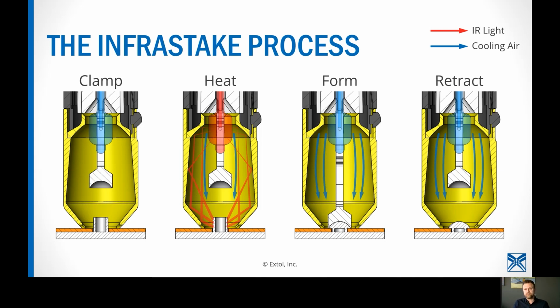Well, and that's important to point out, because not only is it not heated, but that's one of the things that makes InfraStake work so well, is because it is not heated. So plastic naturally will not stick to a cool steel. So the punch is made out of stainless steel. So if we keep it cool, we prevent sticking. So that's a huge portion of it. Not only is it designed not to be hot, but it's used in the process.